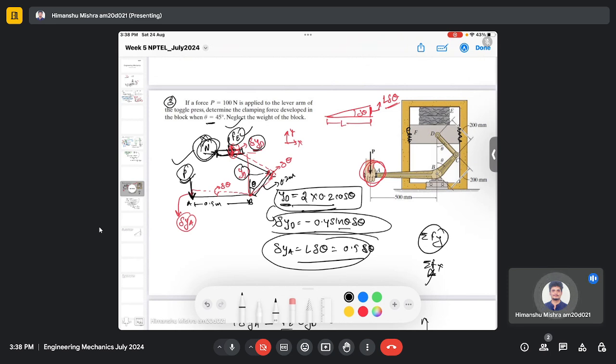It's a similar problem to the one we solved previously. Here we need to bother about the virtual displacement. The complication is actually arising from the way we are calculating the virtual displacement. Here we already know this YD, which is 0.2 cos theta twice, and there is a little change from this distance YD, associated with del YD. So del YD is the virtual displacement which is caused by the unknown force Fe.